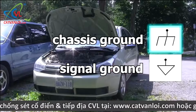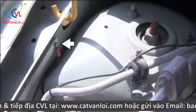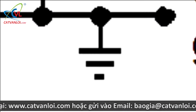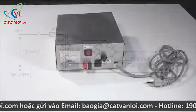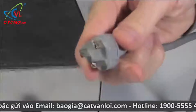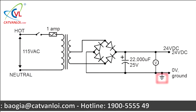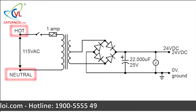This one means chassis ground, such as the chassis of a car, basically a continuous piece of metal that many things in the car are connected to, including battery negative. Sometimes, though, the ground symbol does actually refer to connecting to earth ground. This is the schematic for this power supply, one that you plug into a wall, with a plug that has a ground prong. In this case, the symbol is saying to connect to that ground prong. Well, I guess the only hint is that these points are labeled as hot and neutral, the names for the other two prongs in the plug.